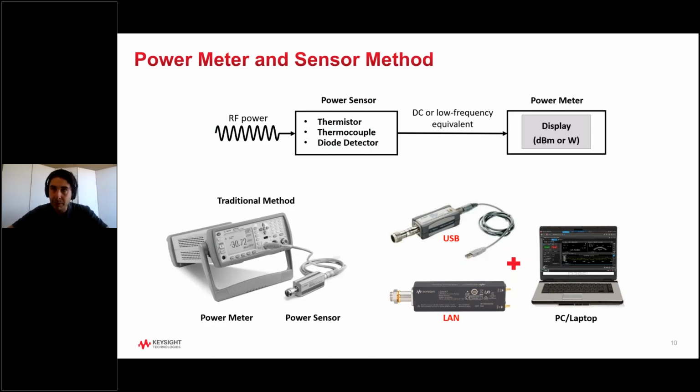Now, I realize that it might be small, but if you focus in on the laptop display, what we have overlaid there is our BenchVue software. And this is our way of being able to have our power sensors communicate directly with a platform which provides ample flexibility for further understanding and visualizing your power. We can see our power displays as an analog readout, as a digital readout. We can look at how our power varies over time, like a strip chart. And in some cases, we can view our live traces.